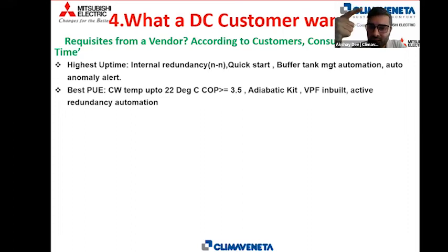Adiabatic kits in places, especially where there is less humidity, places like Bangalore, Hyderabad, dry climates, very, very useful to increase the chiller efficiency. Inbuilt variable primary flow systems, your pumps, active redundancy automation.